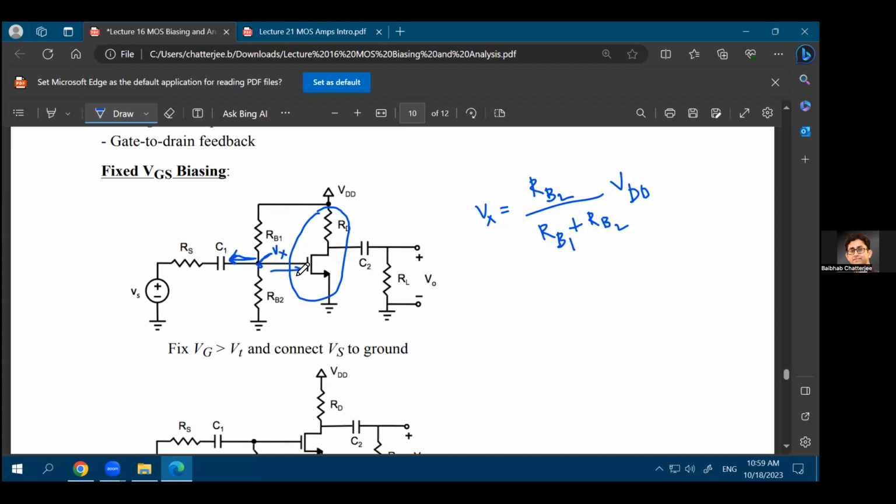Again, on the right-hand side, you see the gate of this transistor. We already discussed that a MOSFET is a metal oxide semiconductor structure, right? So you have a metal gate, and you have some kind of an oxide in between the metal and the semiconductor. This oxide layer stops any current from flowing through. So there cannot be any current flowing into the gate because of the oxide layer, and that means you have an infinite input impedance at the gate. This is very similar to what we discussed with op-amps, that there is an infinite input impedance, and there cannot be any current flowing into the gate.